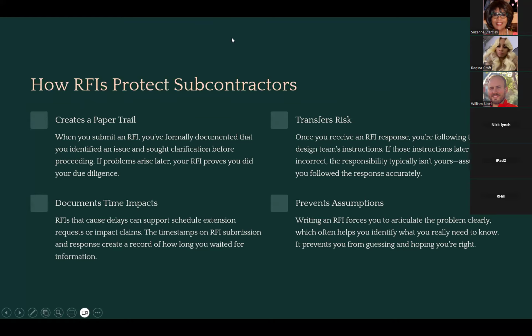How RFIs protect subcontractors. They create a paper trail. So when you submit an RFI, you have formally documented that you think there's an issue with the contract drawings and you've sought clarification before.